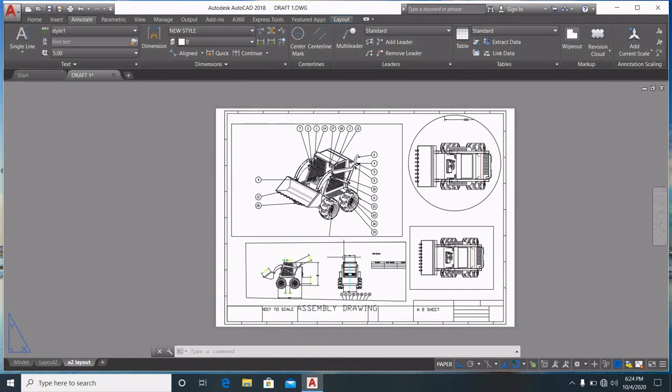Okay, to make it PDF, to export it, you can do it here. To export it to PDF or how to print, in another video I will show how to print, otherwise this video will become very long. So in this way you can export from SolidWorks to AutoCAD and then place it like here.